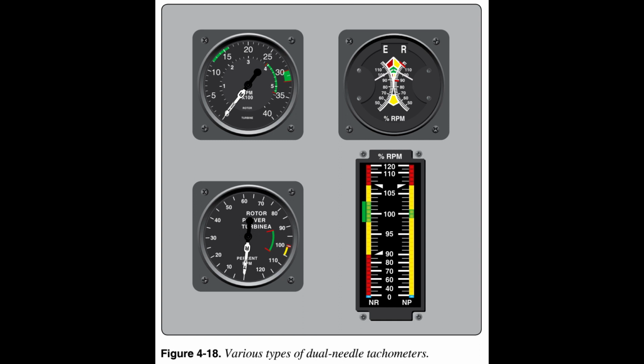If the rotor tachometer fails, rotor RPM can still be determined indirectly by the engine RPM during powered flight because the engine drives the rotor at a fixed 1:1 ratio by virtue of the Sprague clutch. There have been many accidents where the pilot responded to the rotor RPM tachometer failure and entered into autorotation while the engine was still operating.